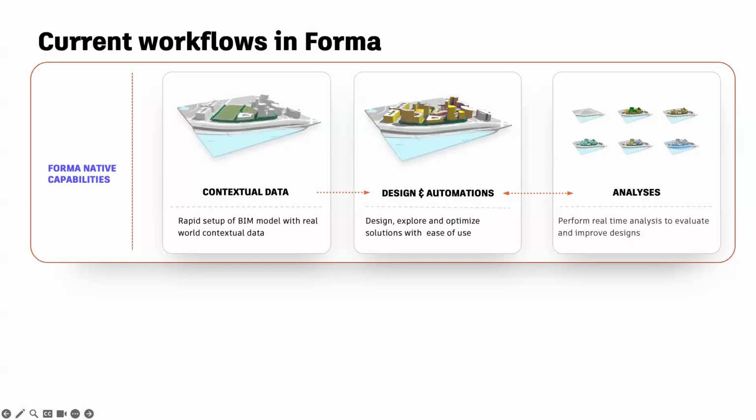So if you discover a wind tunnel in one of your design options, it's much better to fix and edit your massing in the early stage. So later on in detail design, you don't uncover this wind tunnel that's being formed, and it's much harder to change in detail design and construction than when you're in schematic design. You still have the flexibility to do so. So Forma gives you these insights at the very early stage so that you're informed early on what the risks or outcomes are for your project.